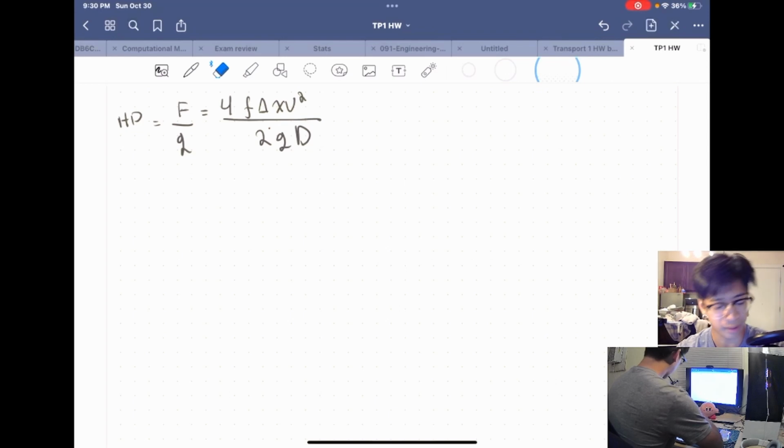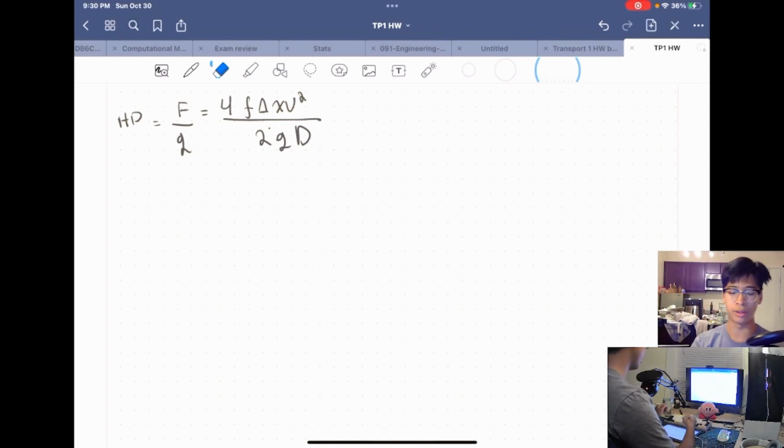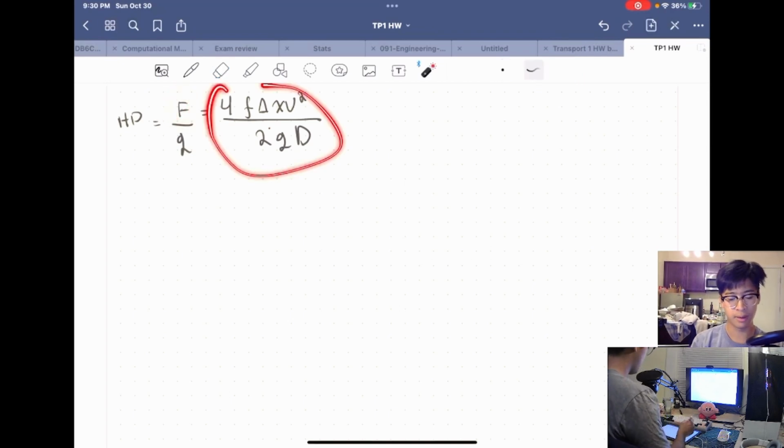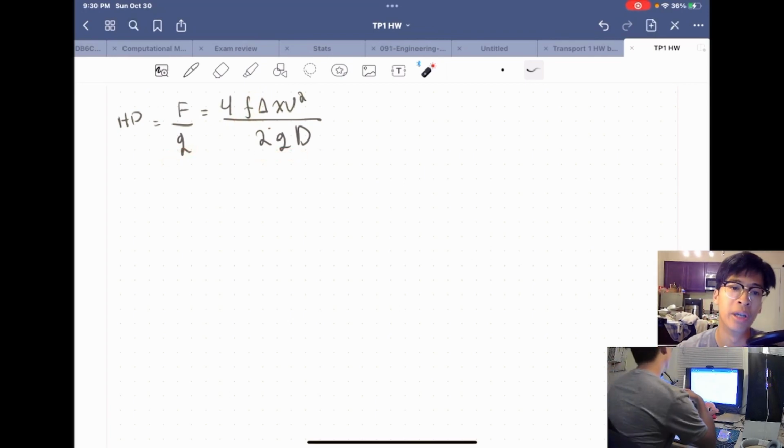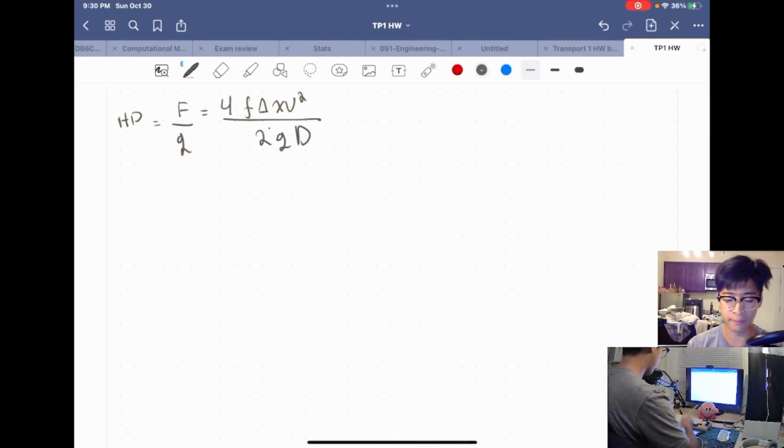And to start off, we're going to bring out our equation, which relates the frictional heating to the fanning friction factor, right? And I've gone ahead and divided both sides by g to get things in head form. Therefore, this expression is our head drop. You'll notice that we don't have Q yet, but we have velocity, and we can relate the two by the equation of continuity.